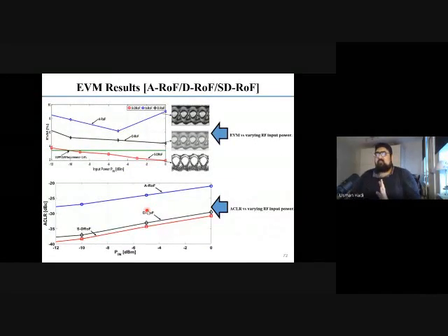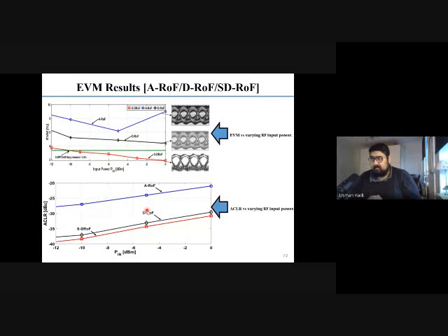And then at the end, I just put analog, digital, and Sigma Delta results. You saw that analog has this result. Then we had digital, which is an expensive choice, but it outperforms the analog one. And then we have Sigma Delta, which is an amalgamated version of analog and digital, but with 1 bit of ADC. And this is actually surprisingly better than all of these options. And that is the best option that we have at the moment for the front-haul communication.